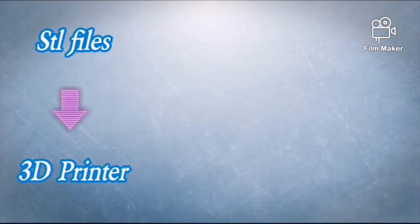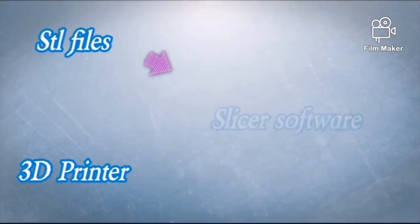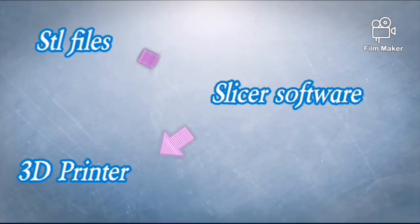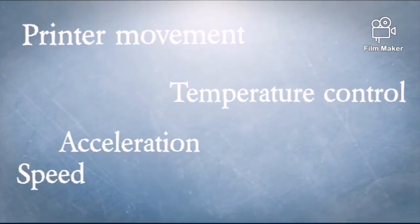Okay, well now imagine that you have obtained an STL model file from an internet source, but how are you going to print this file using your 3D printer? The 3D printer is not able to read this file, so here is where slicer software comes into play. A slicer software helps to convert the 3D object file or STL file into a set of instructions named G-code. Inside the G-code, it contains instructions such as the printer movement, temperature controls, as well as speeds and accelerations of the printing. Using slicer applications, you can tell the printer how to print your 3D parts according to your preference.